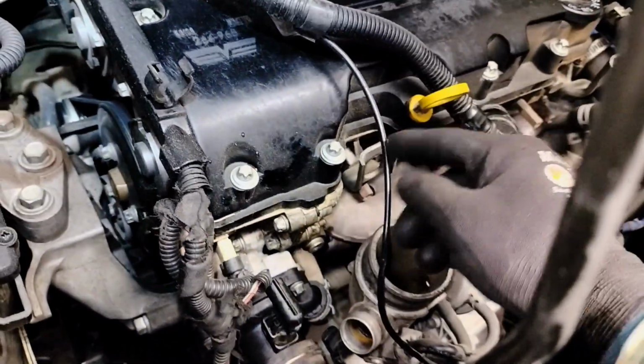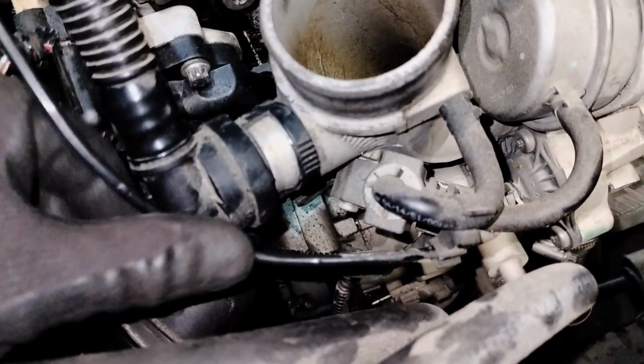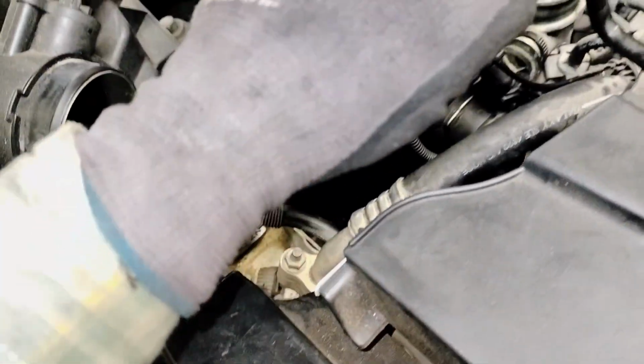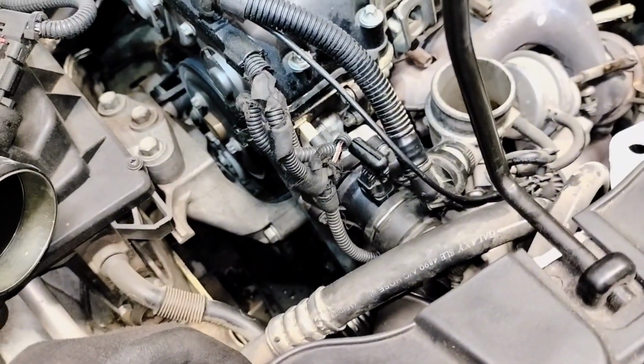Once you got that, then you can go ahead and put the hose that goes here on this side. You just have to push it in, like that, and then you install this where it belongs. Now be careful with these little hoses. They're very brittle. Now it's time to install the air hose that goes into the throttle body. I have already tightened the coolant bleeder plug.